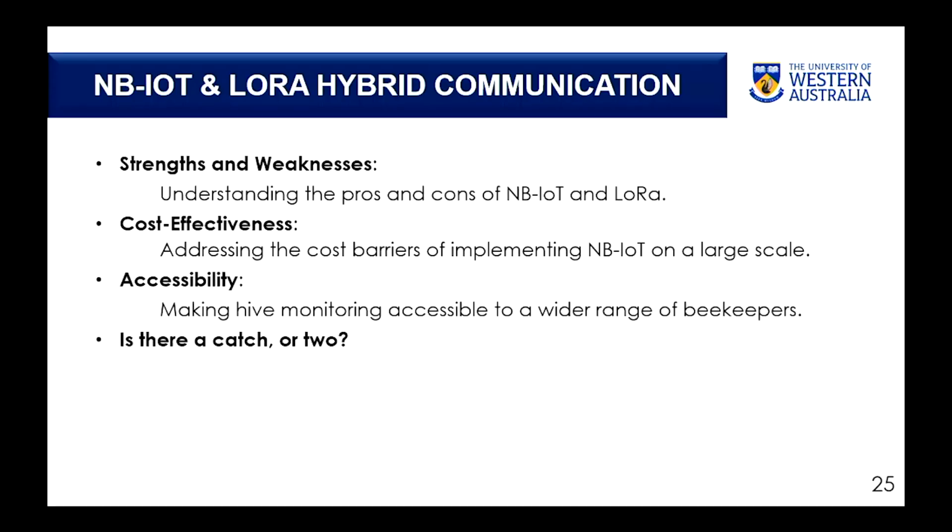Yes. Not only the transmission, but it is also used as a sync node, so it has to be open all the time. It has to be awake and listening to the data from other devices all the time. For other devices, I can collect the data, transmit, and go to sleep. But for the router, I cannot put it in sleep mode. It has to stay awake all the time so that it can receive the data.